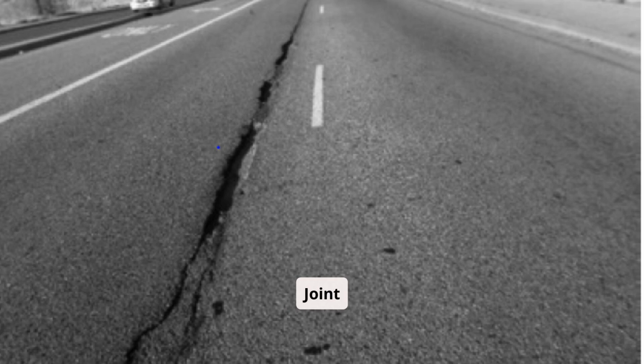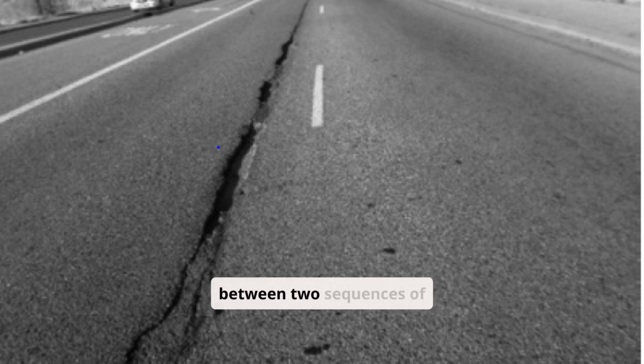Joint separation. Joints are required between 2 sequences of construction. Sometimes, joints are provided between lane and shoulder. The widening of joints may turn into distresses if it is not sealed and moisture infiltrates through it. The figure shows an example of an extreme consequence of a joint separation.